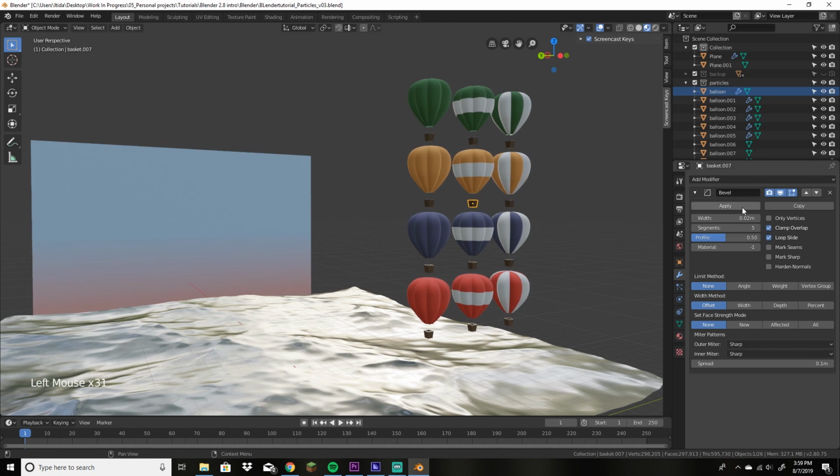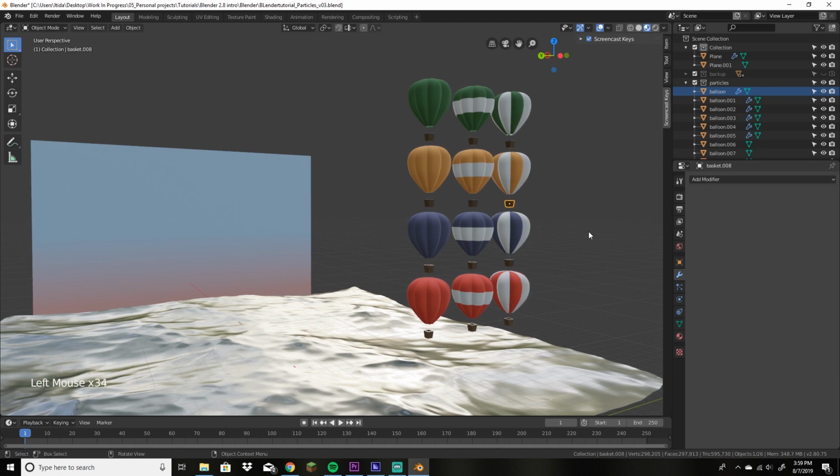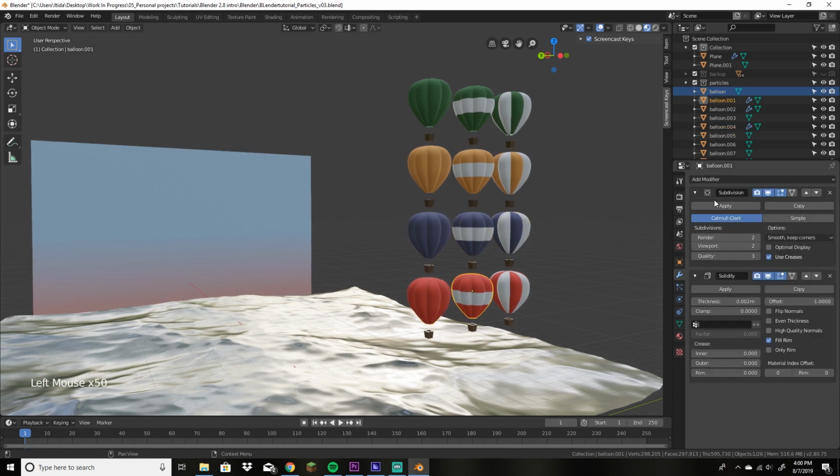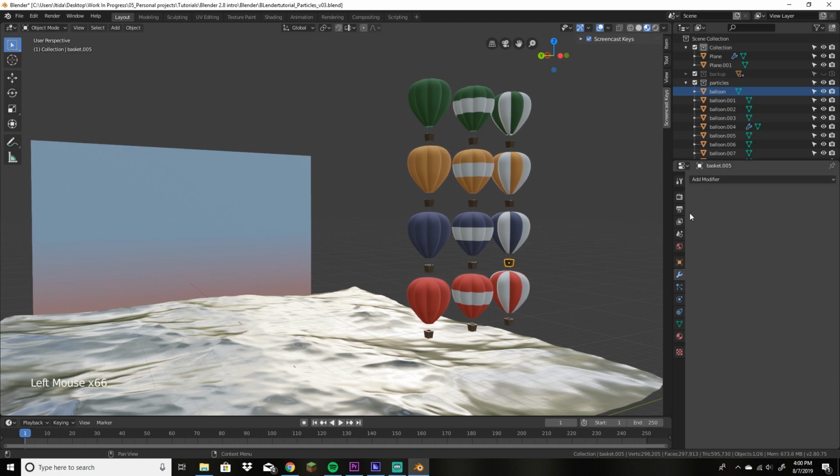It's just better, it's like a non-destructive workflow. All right, looks good. Now, merge two objects. Select one, select the other. If you were to box select this and try to join these by hitting Control J, it wouldn't work because one of them has to actually be active.